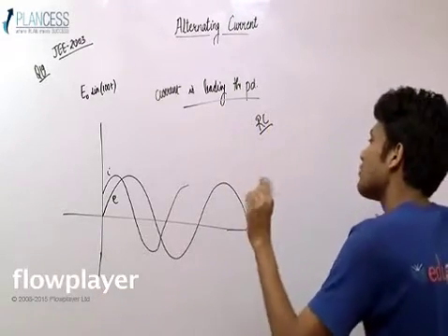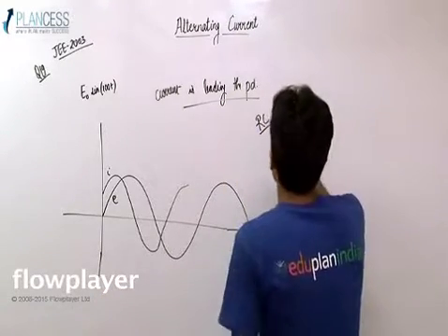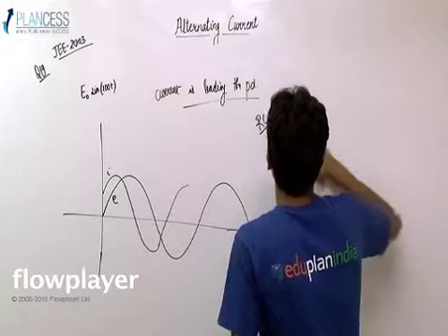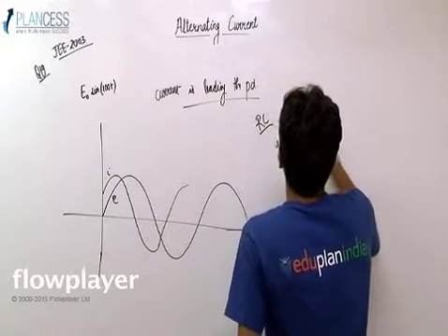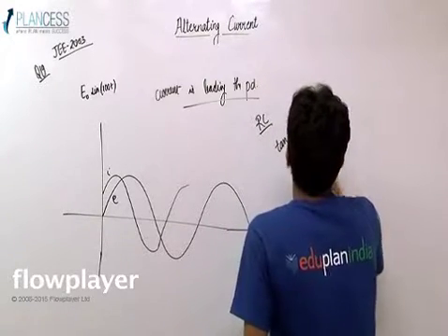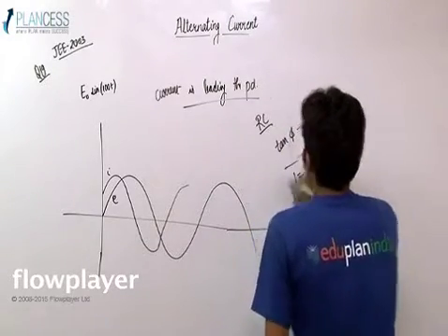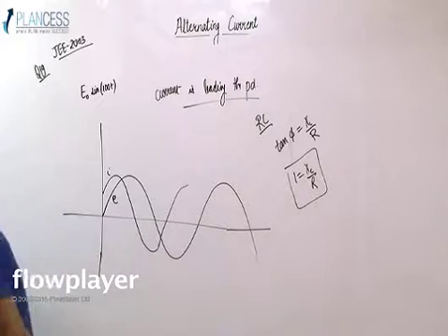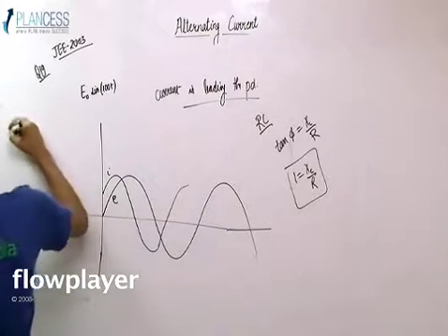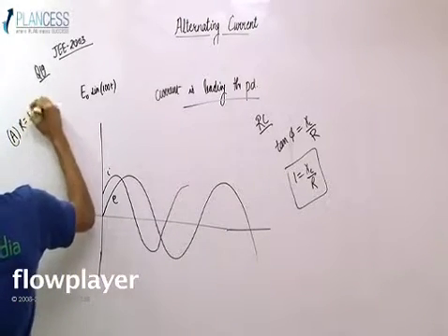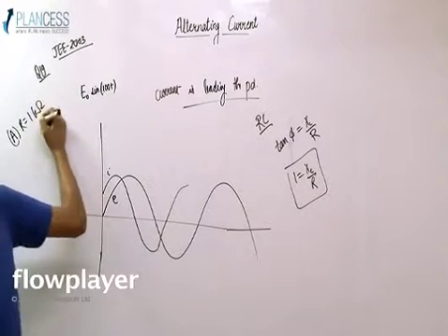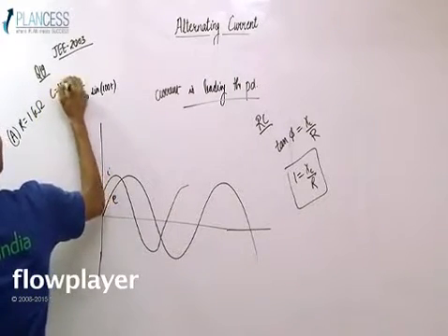Now it is given that the phase difference is pi by 4. So we know that in our RC circuits, tan phi is equal to XC upon R. So tan pi by 4, which would be 1, would be XC upon R. Now 4 options were given in this question. First option A is that resistance is 1 kilo ohm and capacitance is 10 microfarad.